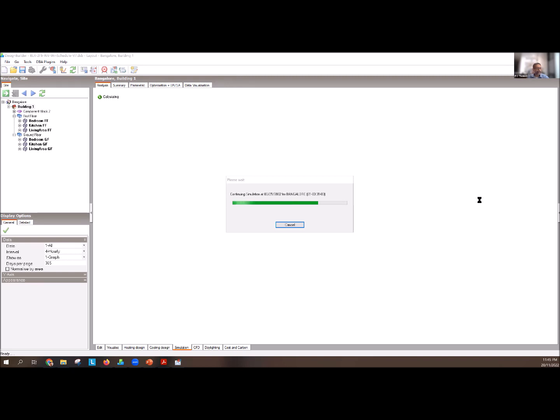But of course, when you are looking at your building in entirety, then you can try so many other things. If the building had a lot of windows, then I would try to either shade the windows or improve the performance of the building windows or reduce the window to wall ratio. So many options are available. But when you are doing real buildings, you need to look at specifics on that building.